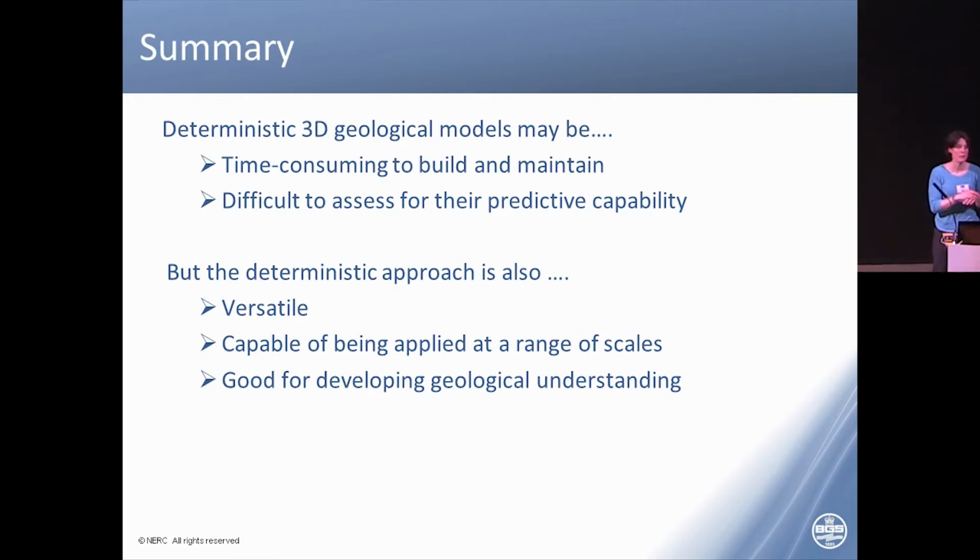In urban areas it can be very difficult to get a good digital terrain model surface. There are often issues with how the borehole start heights relate to that DTM, and sometimes they're real because the ground surface level has changed, and sometimes it's because the resolution of the DTM you have to use isn't sufficient to quantify that properly. So that's something we're working on, looking at the uncertainty associated with those boreholes.